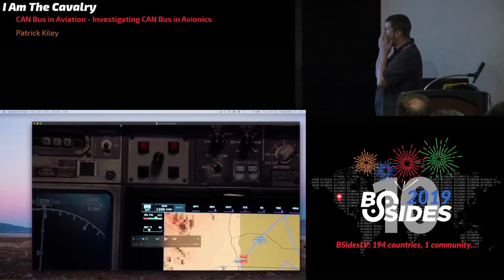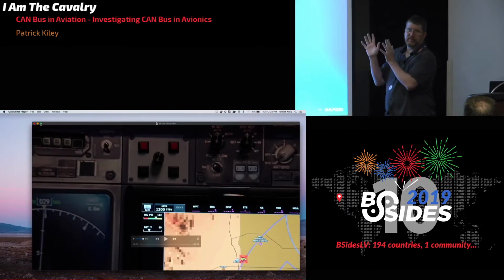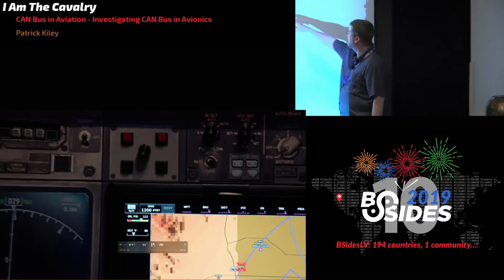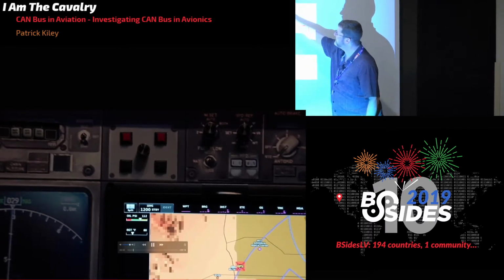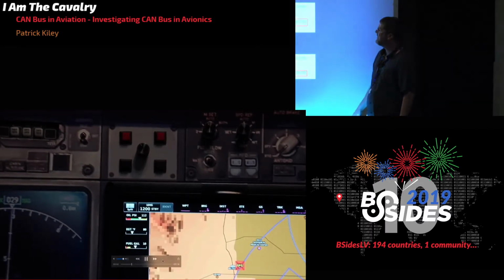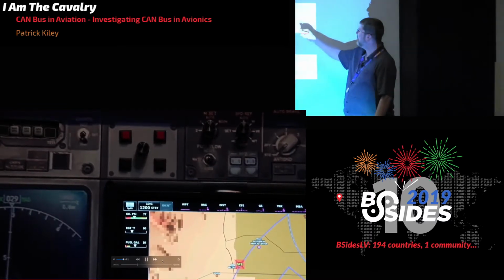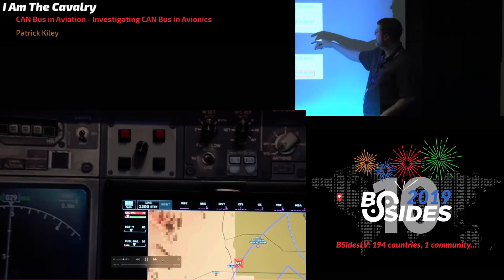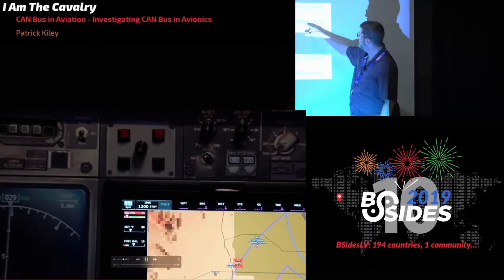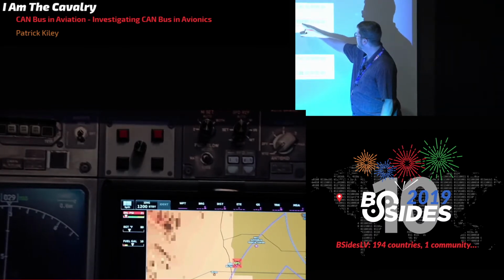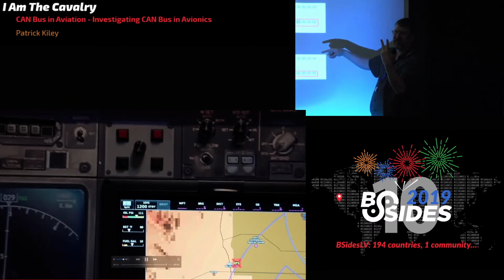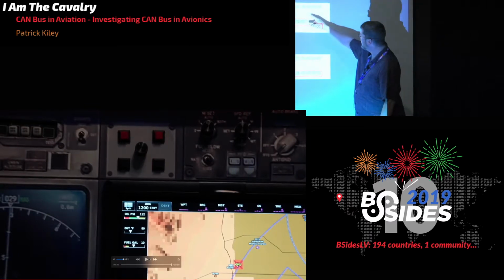And this is basically how the autopilot system on this particular system works. You have a static message for a steady state, which it's sending out at a common rate of about 10 times a second. And then when you engage the roll and pitch servos, because I only had 2 for this kit, you'll see this message come out. Basically, this means engage servos, and this 3 is 2 single bits to engage the 2 different servos.